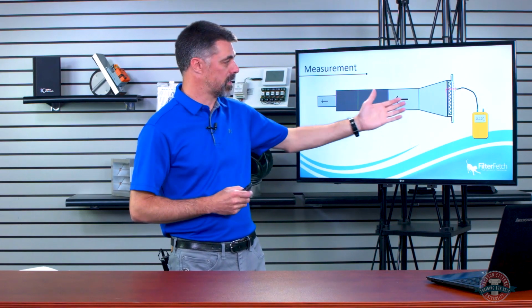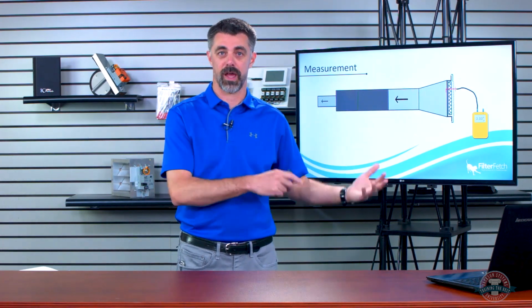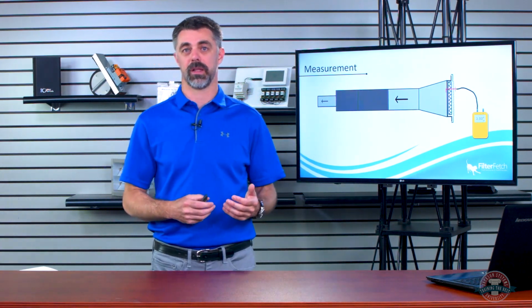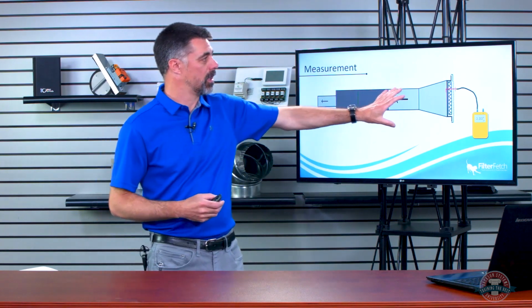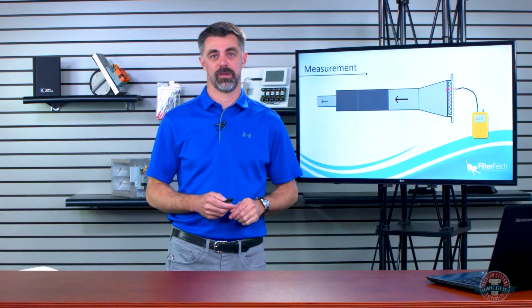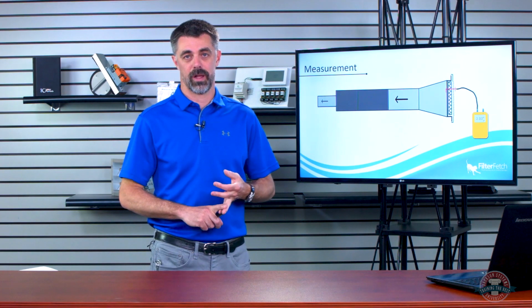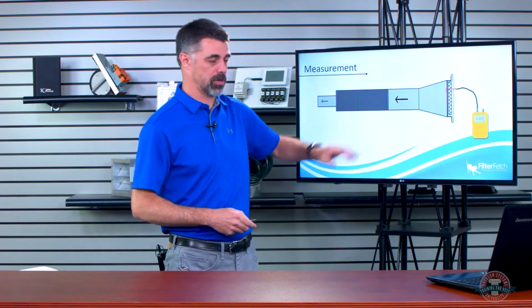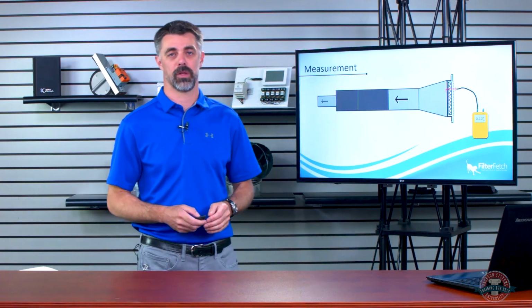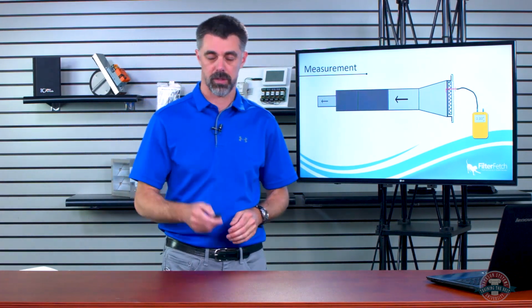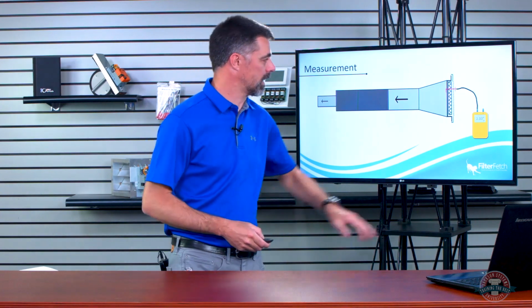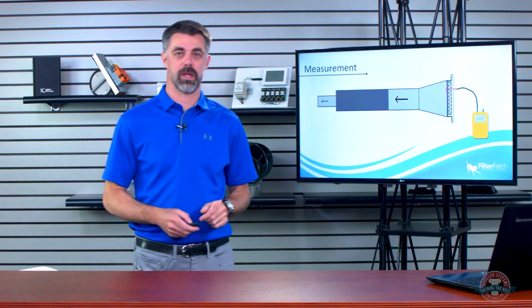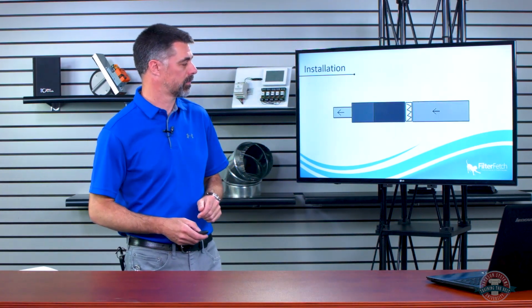This is a really convenient place to put things if you have, in markets where they have package units, they sit outside the house. Or if you have units in attics or a crawl space or something like that, it's a great way to do it. You just have to make sure that that duct is sized properly as well as sealed very, very well. You want to do a duct tightness test on that to make sure you've got as many leaks as possible sealed up on that duct. Okay, and again, we want to look at that kind of 0.1 inch range on that filter there.